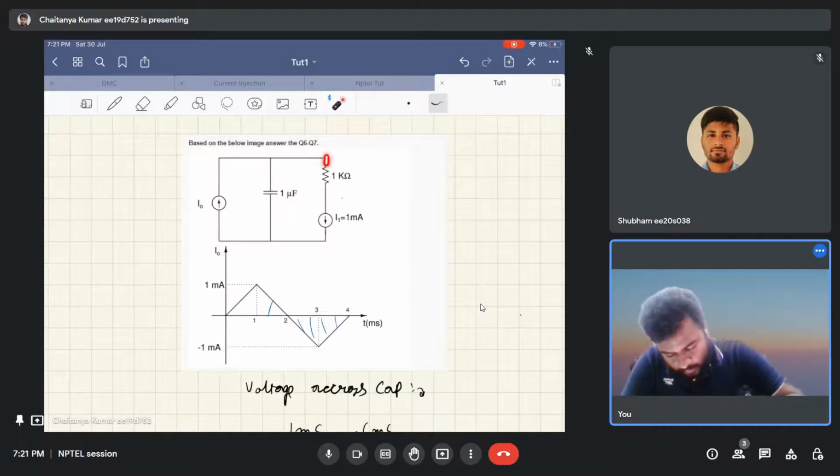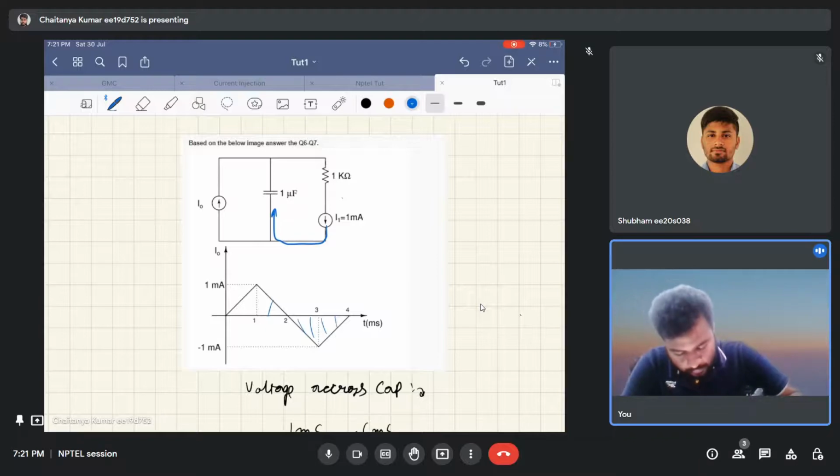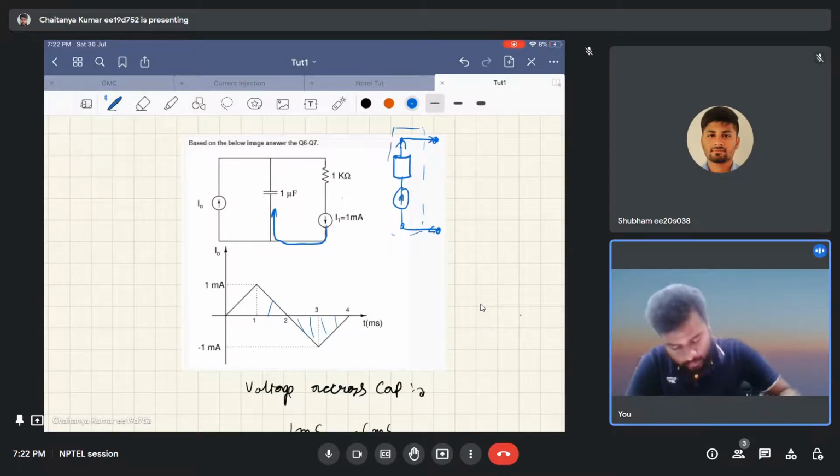Now the resistor that is in series with this current source doesn't have any impact, as irrespective of this resistor, this current will flow in this capacitor. One thing you can always keep in mind is that an element in series with an ideal current source won't change the current that comes through the source across its terminals.